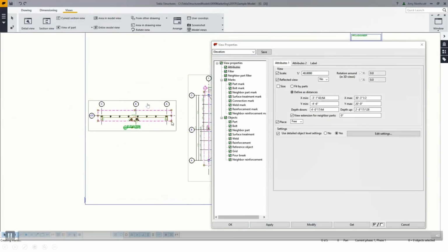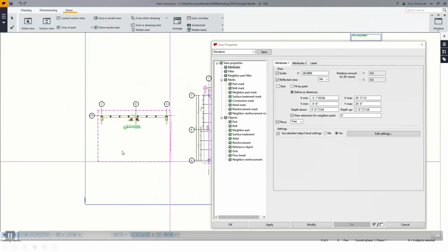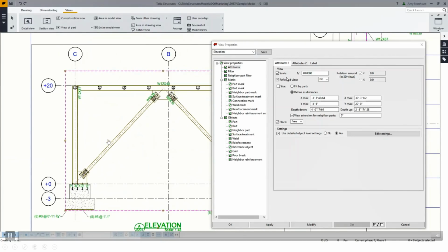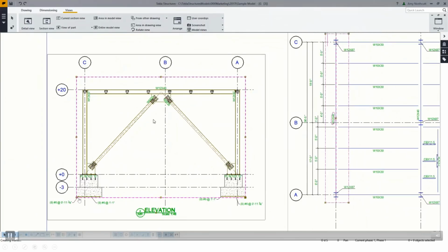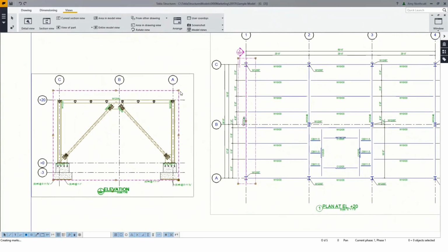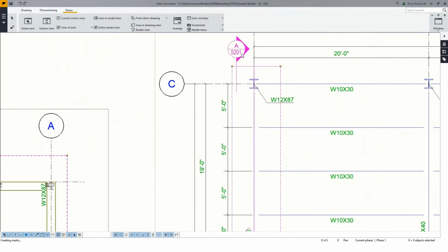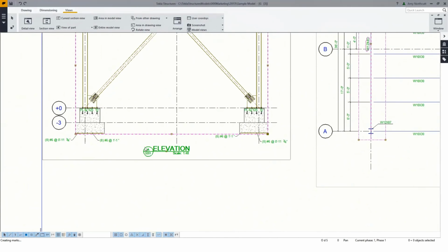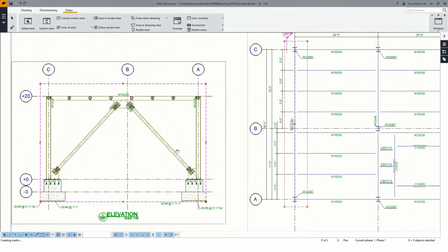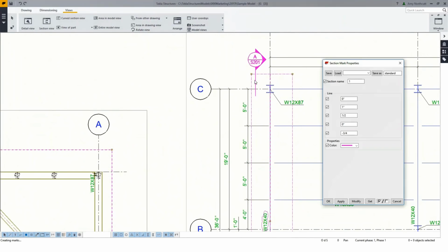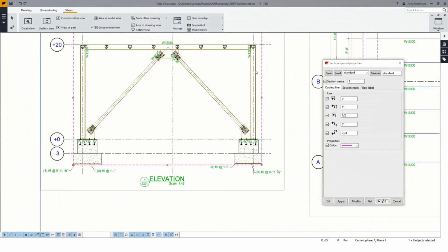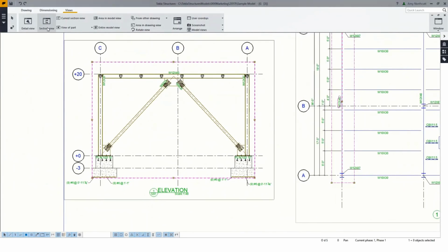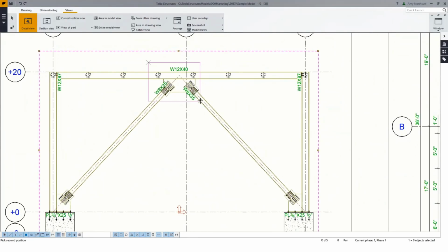And now the pink view extents here. As I'm dragging those, you can see they're updating over here on the right hand side, and we'll see that a little bit more in a moment. But this is really just showing what area of the 3D model I want to see in this 2D view. So grabbing the pink handles allows me just to affect that really easily. Now the labels here, you can see I've got, this is called section A on S200, but if I change that to section 1 on S201, that updates in both areas. That updates on the elevation itself as well as the section cut.